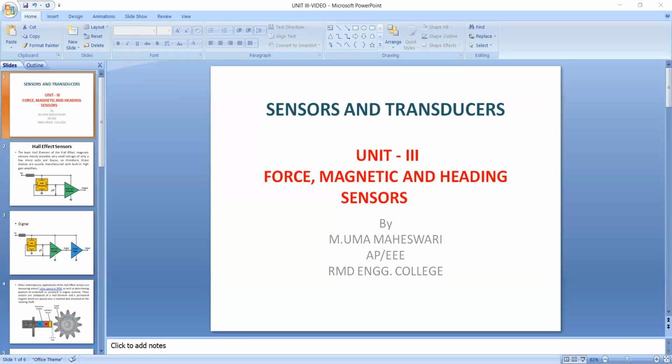So the output of the sensor is a square wave signal, which can be easily used for calculating the RPM of the rotating shaft. So what are the different applications of Hall effect sensors? Analog Hall effect sensors are used for sensing the availability of power supply, motion sensing, sensing the rate of flow, sensing vibration, sensing voltage regulation values, wheel speed sensing for the anti-lock braking system, and direct current sensing in clamp meters, also known as tong testers.